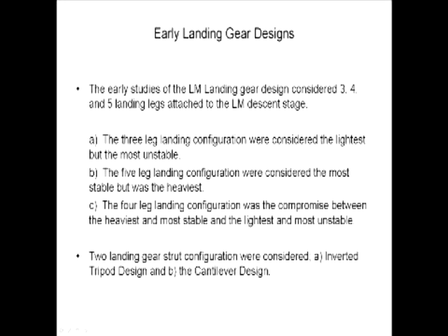We started out with 3, 4, and 5 legs designs, and we started out with an inverted tripod, and then you got to what they've got right now, the cantilever case, which is the 2 secondary struts attached to the primary strut. After iterations on that, we considered the 3 legs to be the lightest but most unstable, and the 5 legs to be the heaviest but more stable. So as you can tell, what's left over? We went to the 4-legged.